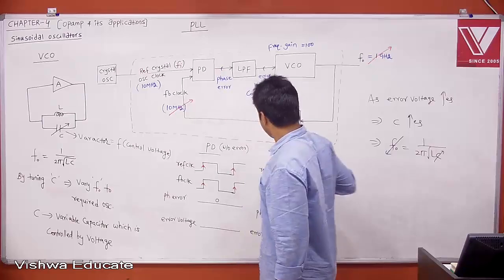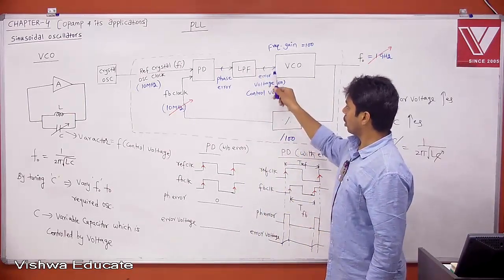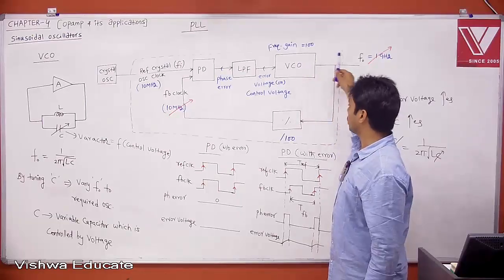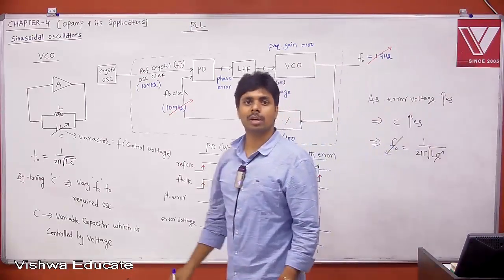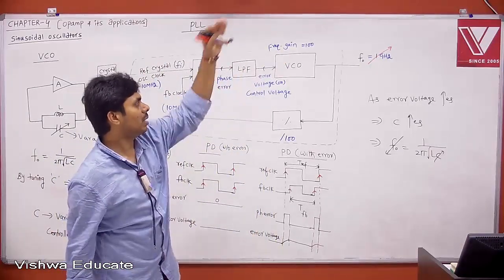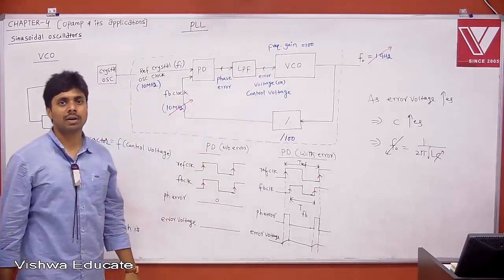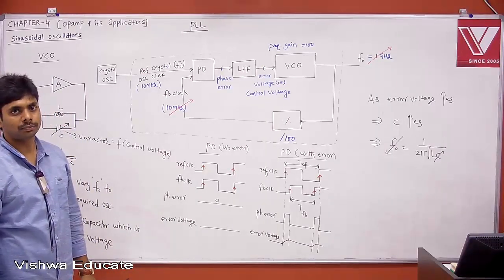Then you will get a pulse, something like this. Whatever pulse you have is converted into a voltage. The voltage will be converted to a sine wave, again sine wave to square wave. But if you want to use sine waves directly, that is what people call a CML clock, common mode logic clock. The sine wave can be sent directly to whatever circuit is asking for the clock.